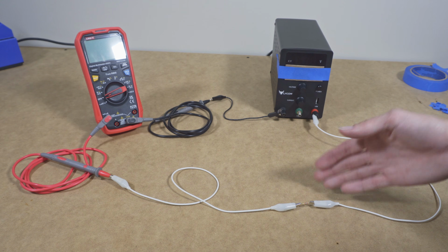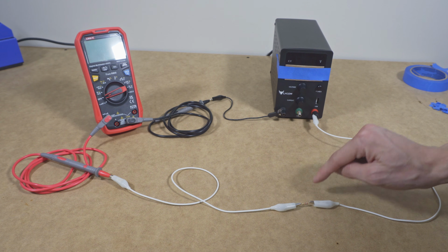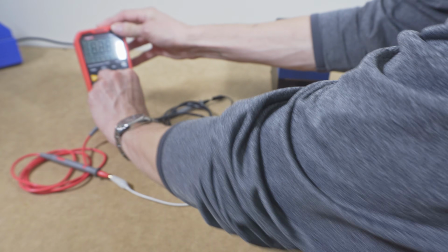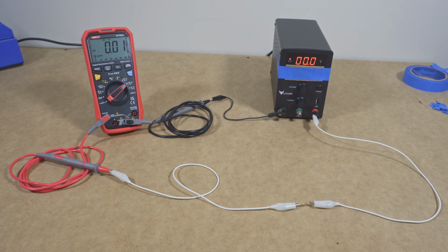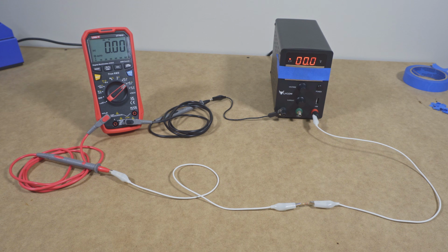Here I have a 2000 ohm resistor, and if I want to flow a particular number of electrons through that resistor every second, as in I want to reach a particular electric current as read by this ammeter, I have to apply a particular voltage. You might think of a 1.5 volt battery or 6 volt battery or 9 volt battery or a 12 volt battery, or all the different sizes of batteries. In this case, let's say that I want 3 milliamps, or about 2 times 10 to the 16 electrons per second flowing through that resistor.